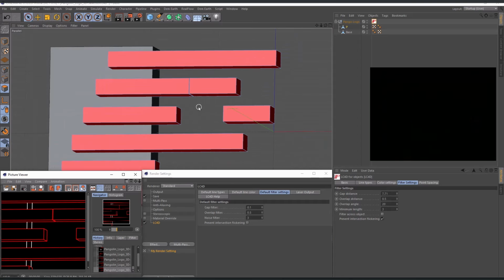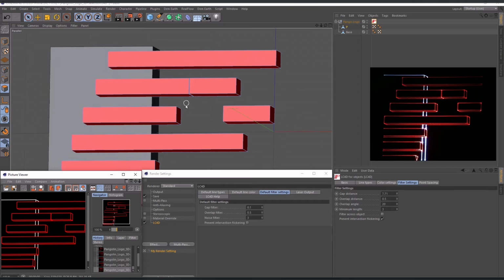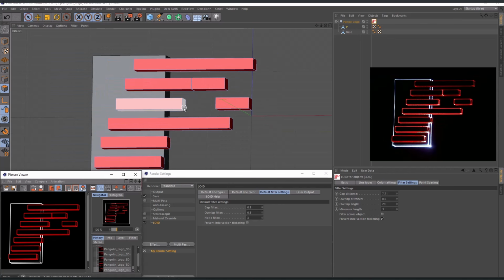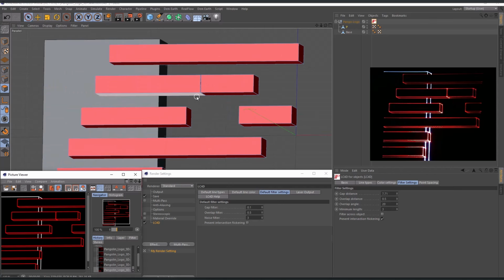So let's do it stepwise. And still 2 lines visible, but I clearly recommend to do this in small steps, because you don't want to filter out too many details of your graphic. And after increasing this further, we see that somehow later those initial 2 lines are now shown as one single line, but as mentioned before, this minor difference will not be recognized by the audience, but will for sure reduce the flickering of your graphics due to the point reduction.